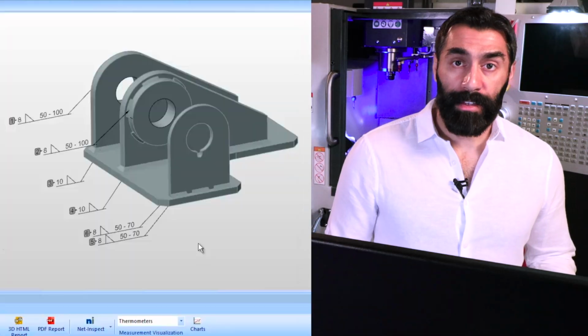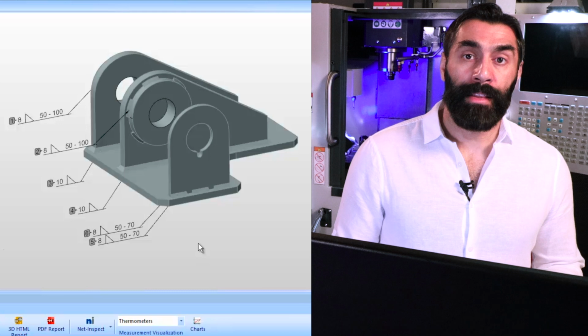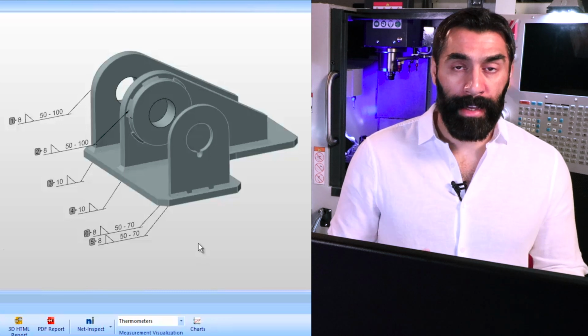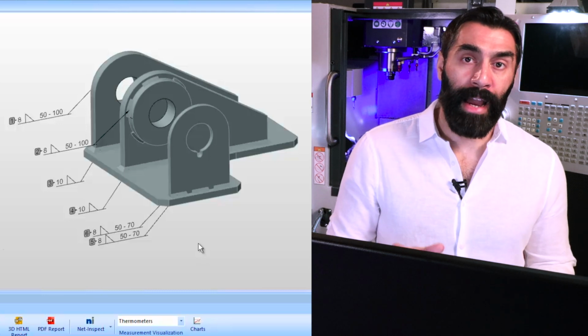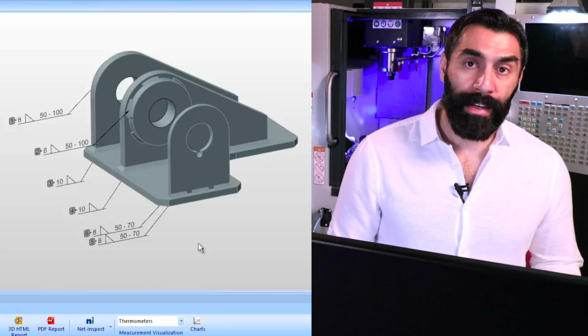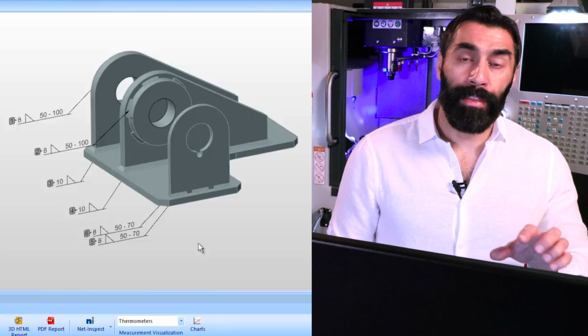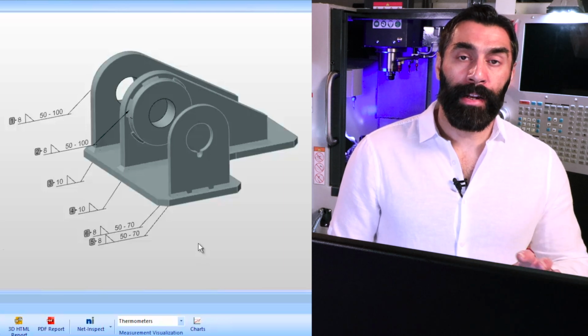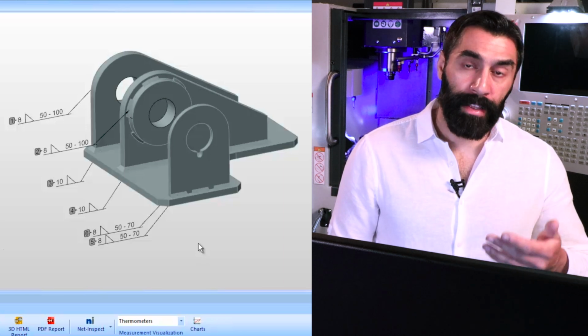In our particular case, since we have this Smith bracket that has 2 eye plates on it and the additional support bracket, we're going to create a separate program for the eye brackets, pre-weld the washer plates on them, and then we're going to weld all 3 of the plates to the main base plate. So we'll go ahead and open up the CAD design, and then we'll go ahead and load the QIF weld information that's contained within that QIF file.